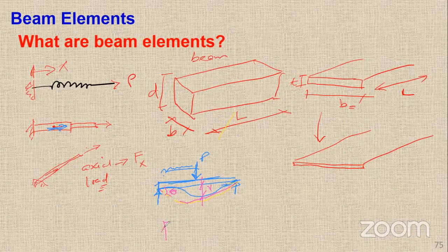Of course, if it's fixed, if your beam is built in here, then it deforms like that. Then there's no rotation of the support. I know you already know this because you've been handling beams and different kinds of supports. Therefore, for the bar element that we talked about, there was only 1 degree of freedom per node, a 1 degree of freedom element in the local coordinate system, which was the axial displacement.